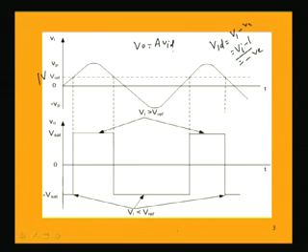So, this will be negative and it will be limited to the saturation voltage, around minus 14 volt for the 741 IC. We denote it by minus V sat, that is the saturation voltage in the negative. So, that means for this portion from 0 to the point where Vi is less than the 1 volt reference voltage, the output voltage V naught will be saturated at minus V sat. So, this is the reason.